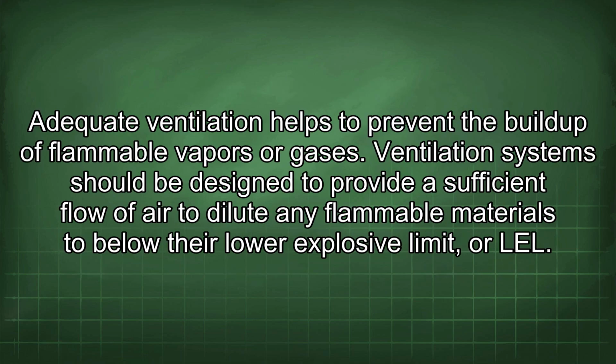Adequate ventilation helps to prevent the buildup of flammable vapors or gases. Ventilation systems should be designed to provide a sufficient flow of air to dilute any flammable materials to below their lower explosive limit, or LEL.